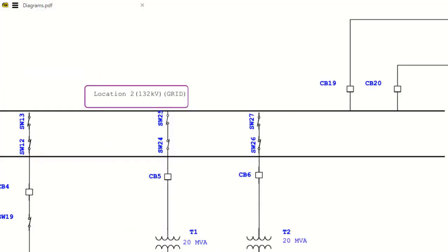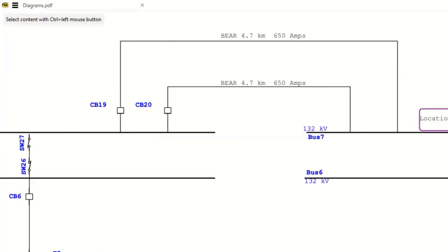So you'll use the same references you used there to replace this cable with an impedance value. Remember, it's an impedance, not just a resistance. There will be a resistive element and an inductive element in the cable. Together, that will give you an impedance with the power factor, whether lagging or leading. But you will decide what you get there.